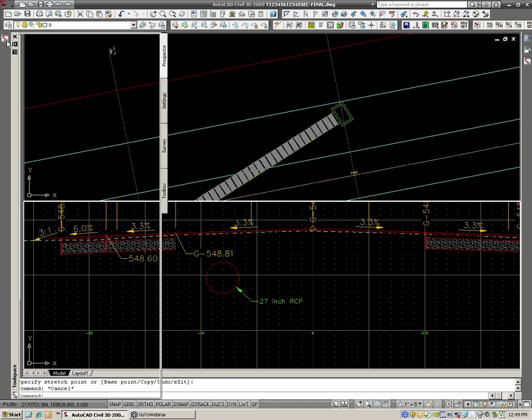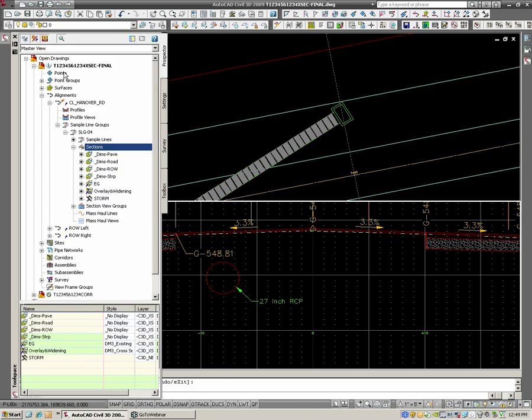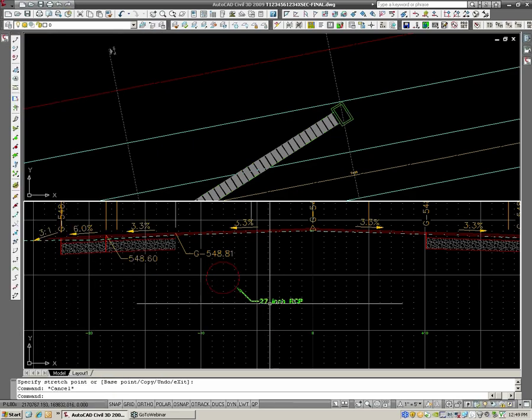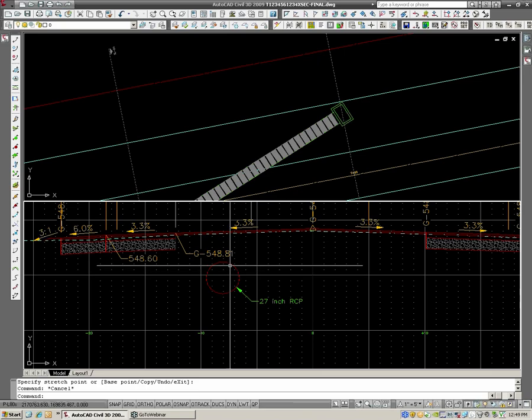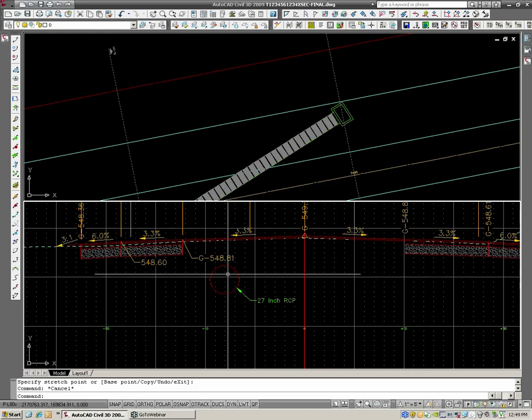You'll go over and hit synchronize data references, and then they will show up, but the labels will be gone. I think how Josh is handling that is he's labeling them, and then exploding this label so it stays, and then he just remembers to hit update data reference when they don't show up. Something we could be missing, or I'm sure it's going to get better if that is a glitch with the next release, which is probably already fixed, but just be aware there is a little bit of goofiness with pipes and cross sections.